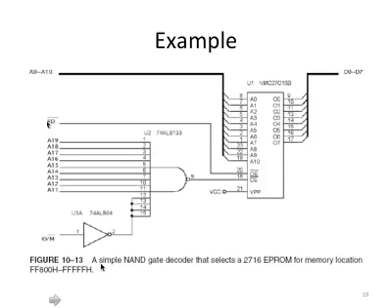So if it is a memory read, let's say you do MOV AX, [BX]. Picture that. This is a typical memory operation, a memory instruction of the Intel x86 instruction set. If you have such an instruction, eventually this microprocessor will output 0 on this control bit to indicate that this is a memory read operation.